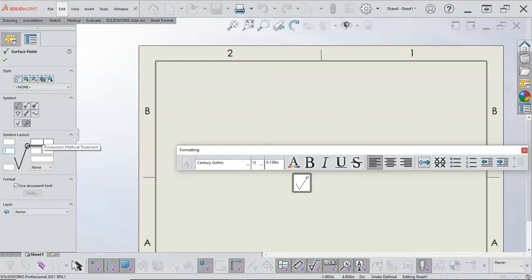And then we get to the production method treatment. We'll take a look at the tech drawing description, but we're using that for waviness. And then the sampling length, 100 thousandths, and then the other roughness values, and then the roughness spacing. And then lastly, the directions, basically if it's a grain or if it's in an area that we want to measure.